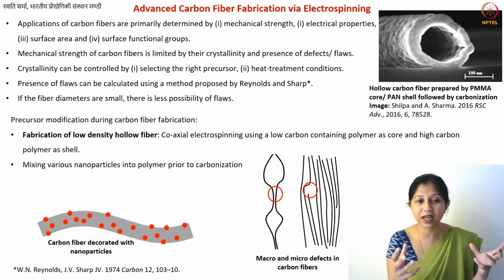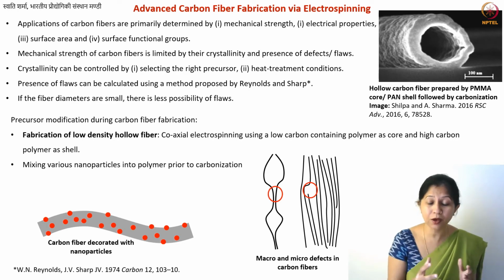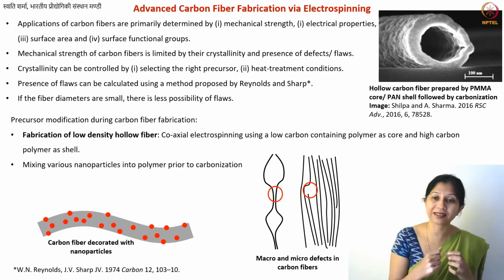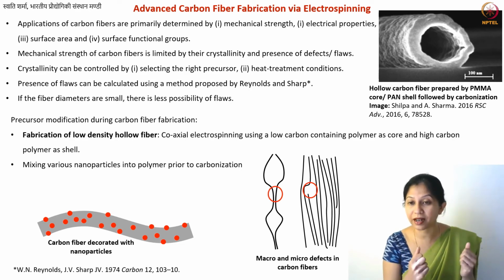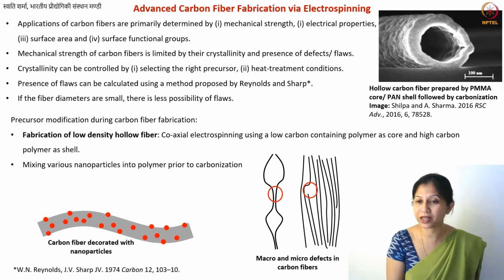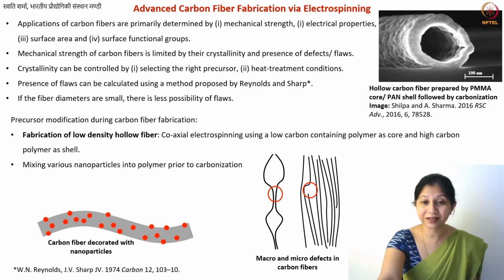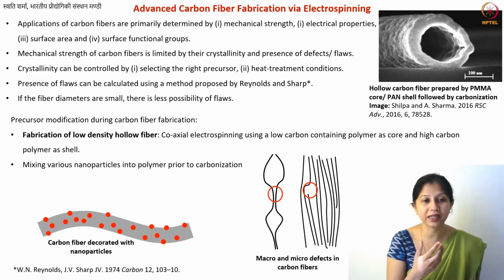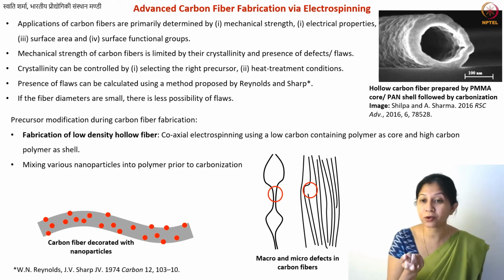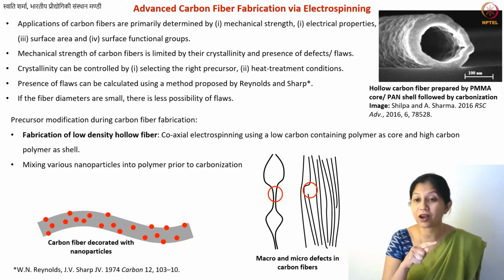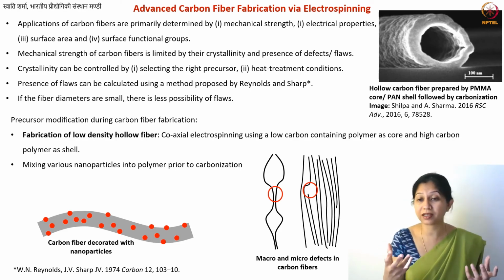These kind of fibers are known as decorated fibers. You will hear this word in the literature, that you have carbon fibers decorated with certain nanoparticles, or glassy carbon electrodes decorated with certain nanoparticles, or many other structures, whether they're large scale or small scale, can be decorated with nanoparticles. So this is also another thing you can do. Why would you do that? Because now your carbon fibers basically serve as a substrate for these nanoparticles. Maybe there is a certain nanoparticle whose property you want to utilize and not that of the carbon fiber, or you want to utilize the property of both.